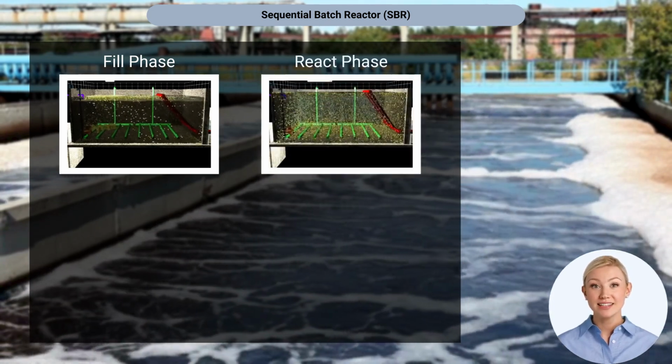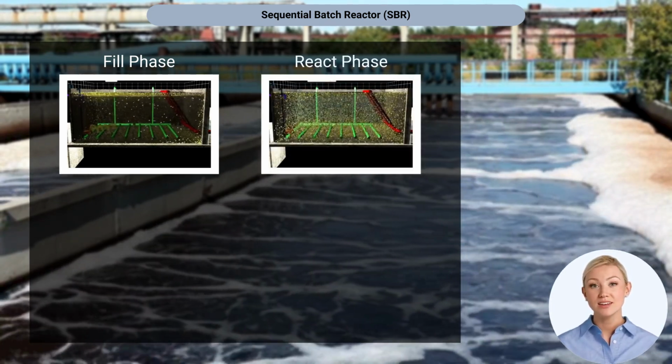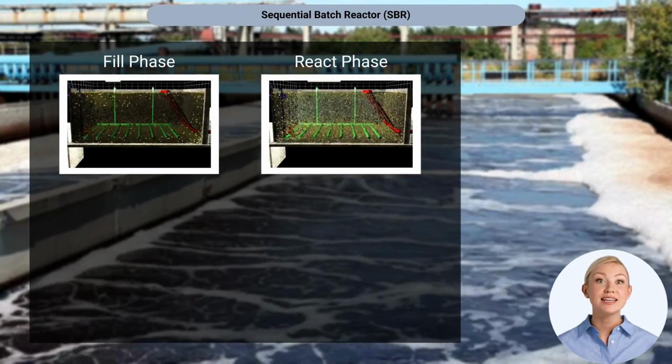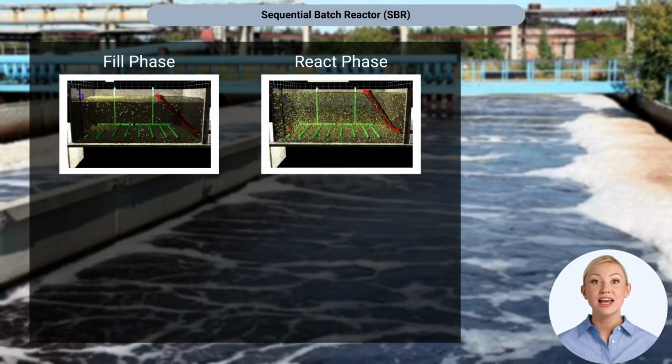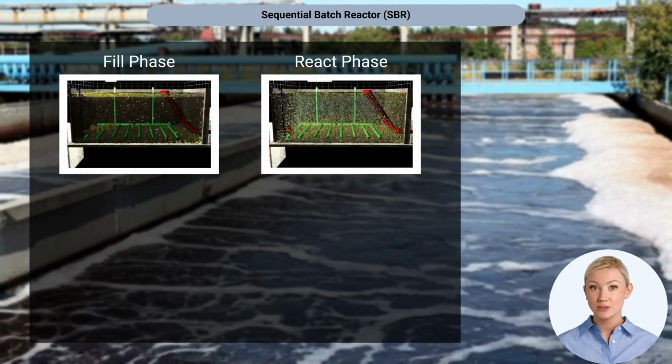Next comes the react phase. Air is introduced, and with it, life. Microorganisms awaken and get to work, breaking down BOD, COD, and ammonia. Some even tackle stubborn dyes, especially when trained to do so.